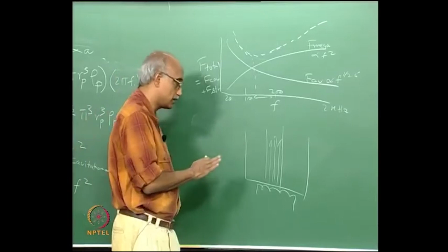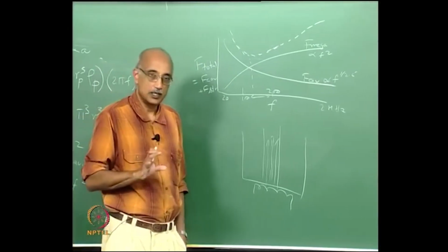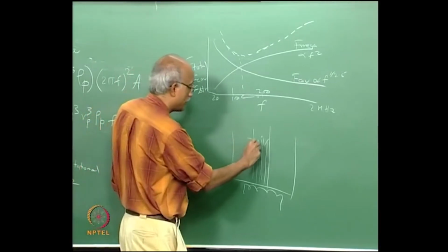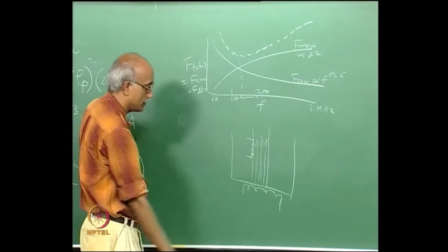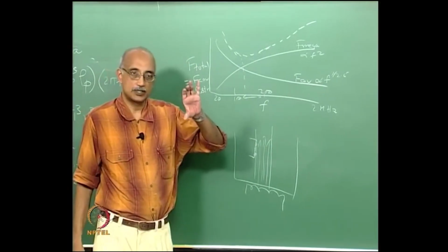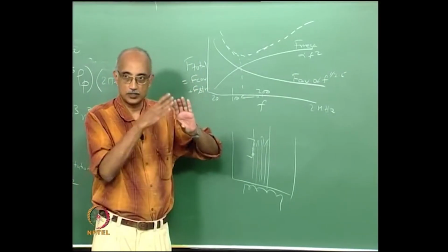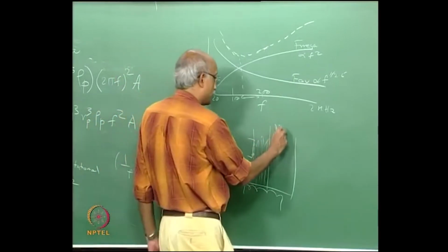So, it becomes very difficult to configure the orientation of the surfaces that you are cleaning in order to get good cleaning action, because the surfaces have to be parallel in order to get a shearing force. So, whatever the direction of the field, you have to be able to mount the surface in such a way that the flow is parallel to the surface, so that you can get maximum shearing action. On the other hand, so this is megasonics.